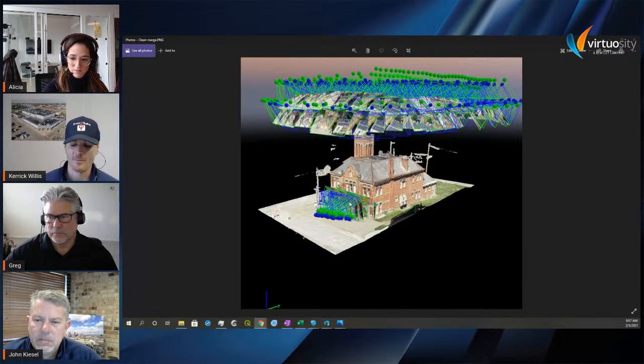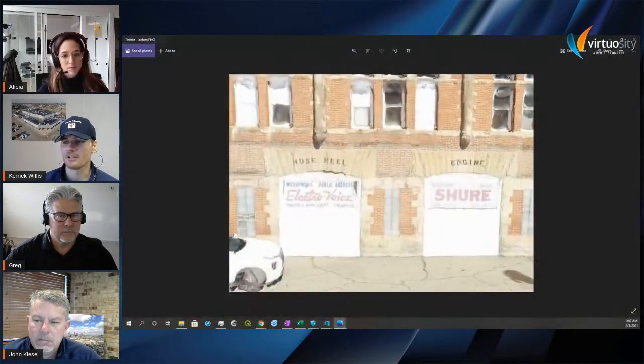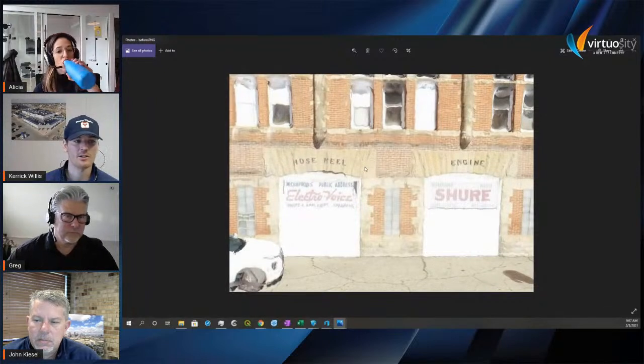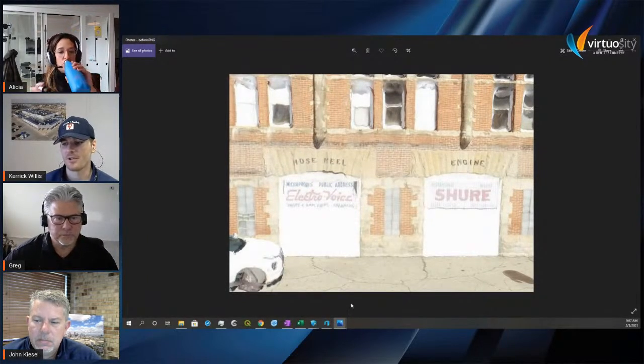While that does make it much easier, this merge wasn't the easiest because of the cell phone GPS data, it's normally a little erroneous compared to the drone data. But as you can see, I did a nadir flight, and then an oblique, and then I shot some images down at the front here in an attempt to get a better looking model. So here's where it looked originally, and I was trying to push into that reality modeling.